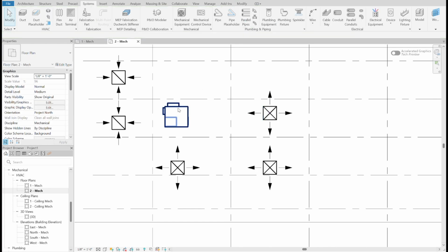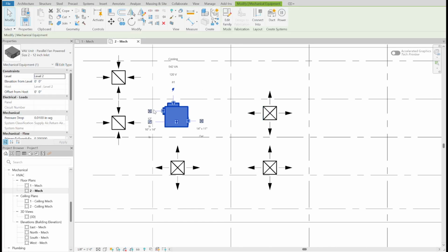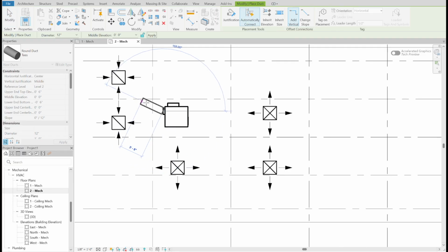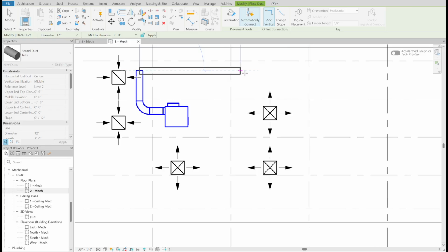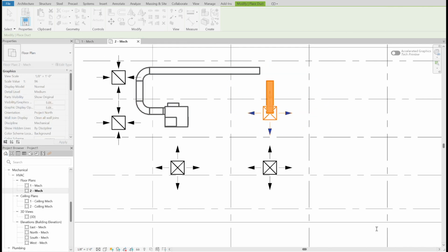The other way is you can select the air handling unit, and you see this little cross. This little cross is showing this is the outlet to the supply terminals, and you see this little single line, and this is corresponding to the symbol of the return terminals. Once you do it, just click this one, and you can start to plot your duct system in whatever way you want. So for example, I want to go this way. And meanwhile, you can see you can change the elevation of your duct system. So here it's 0.